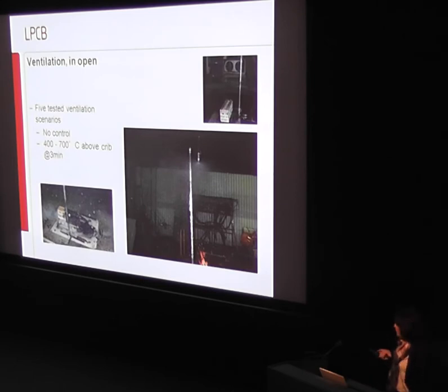We looked at ventilation, and here we had a relatively small ventilator blowing at some distance away, but we got up to about 3 meters per second in some areas, listed in our results. And what you find is the ventilation has two effects. It does affect the fire, so your fire spread across your crib is increased.